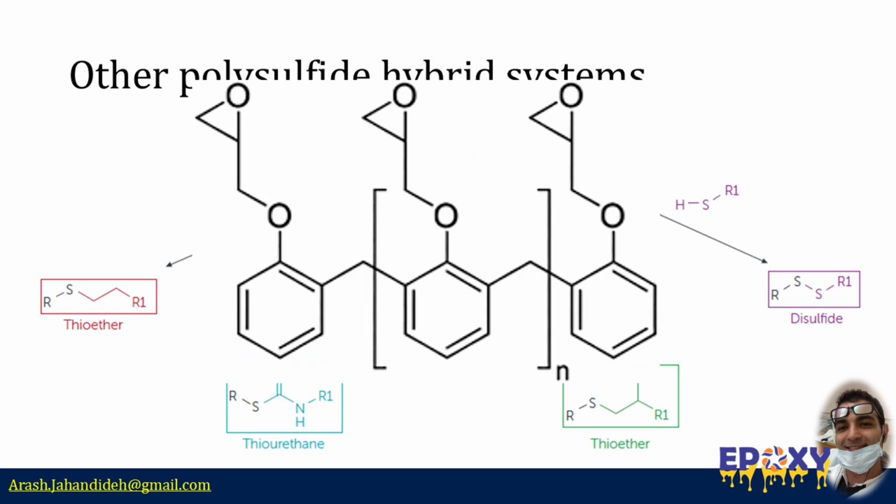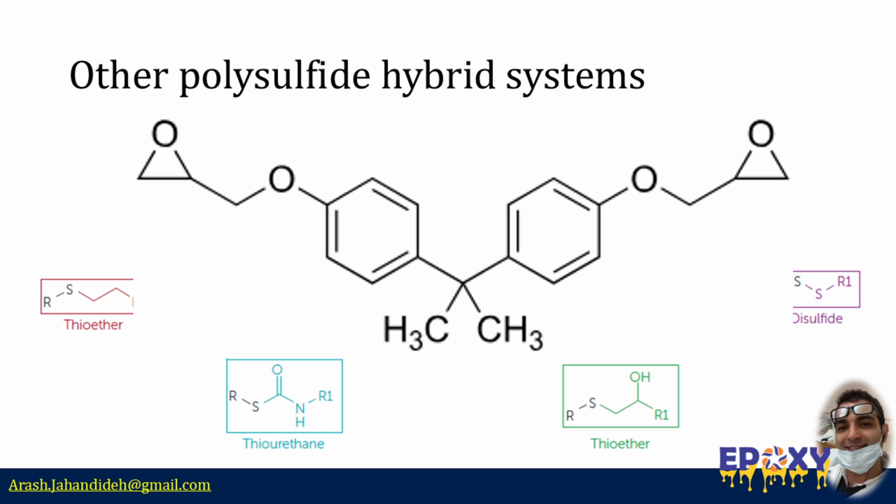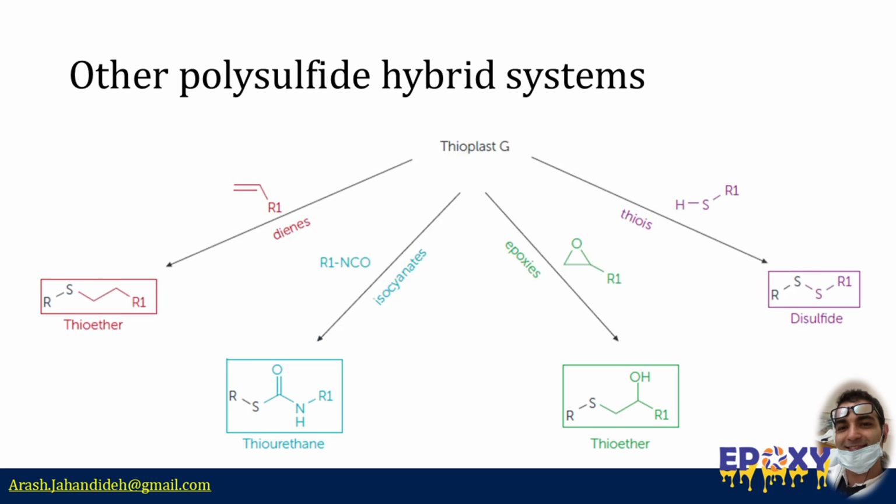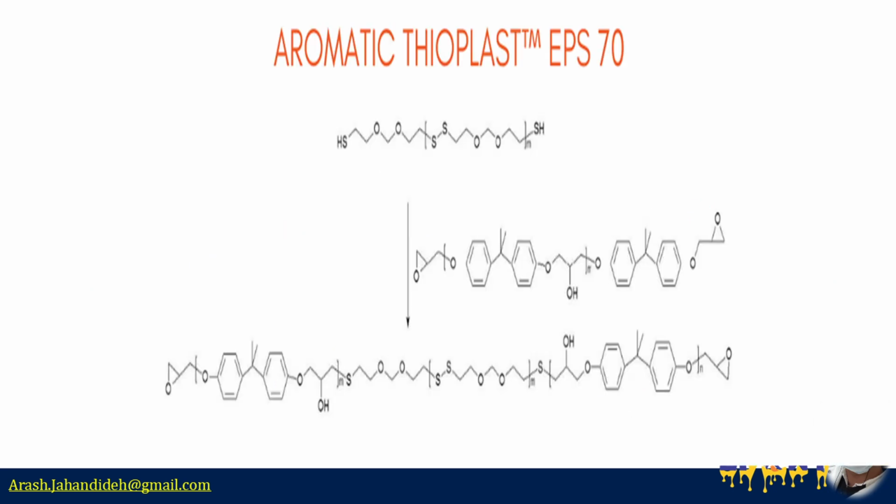1,4-diazabicyclo[2.2.2]octane or DABCO 33-LV, or 2,4,6-tris(dimethylaminomethyl)phenol or Ancamine K54, often with a small amount of ethanol acting as a Lewis base, Lewis acid. This approach yields materials with excellent tensile strength and elongation.